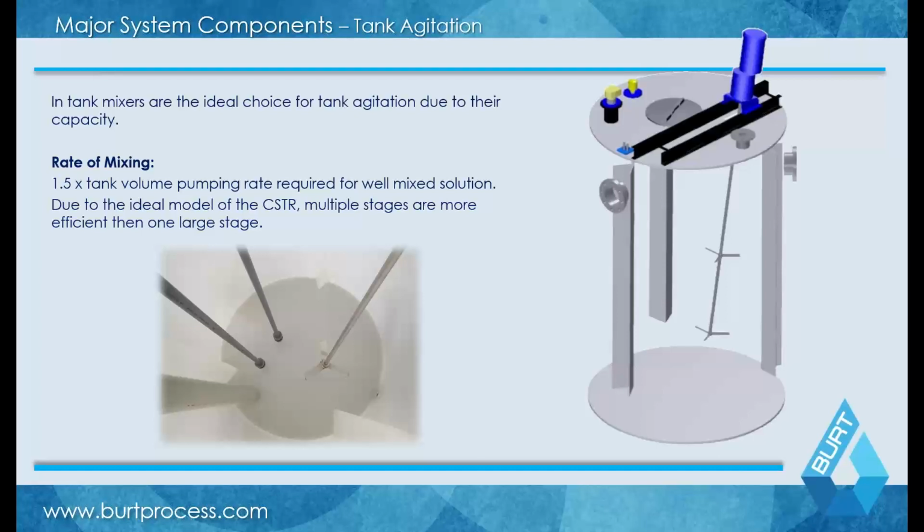Looking inside the pH tank for a moment here, you can see my mouse here. This is what they look like on the inside. This is the inside of a cylindrical treatment tank. You have your agitator here, and your agitator is typically sized for about 1.5 to 2 tank turnovers per minute. So it's not very high agitation in most cases, but it is a moderate amount of agitation. The important thing is you have your waste coming in through a down pipe, which goes right into the mixer, and then you have your chemical injection here. So basically, you're injecting right into that point of mixing.